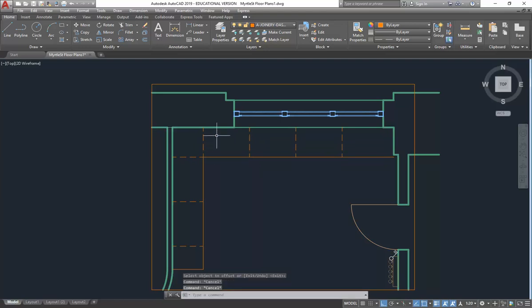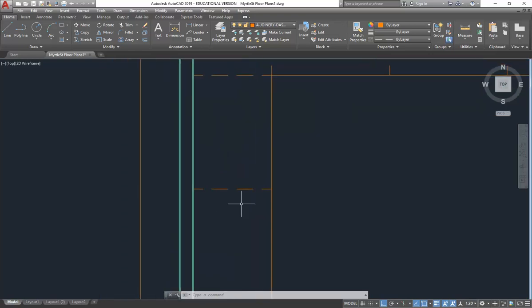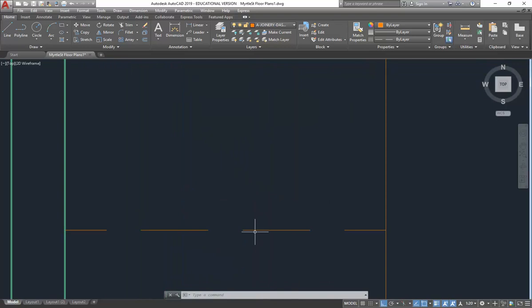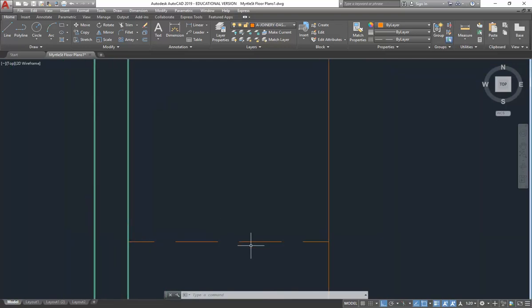And again, it's good at this point to have an idea of your construction type, whether you're going to have a constructed kitchen, in other words, one built on site, or essentially flat pack. And I think the flat pack thing's fine these days. Most people will not even notice the difference until they open the doors, and even then, usually not. So with flat pack, you have the carcass butting up against the next unit. So that means when I offset here, I'll do it 19.